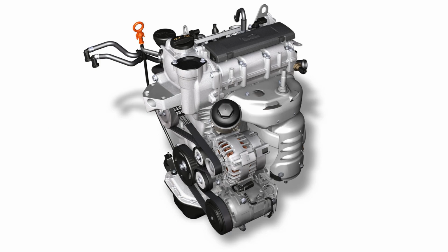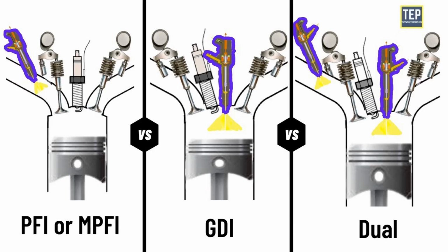Advantages compared to carburetor. Carburetor, mono-injector carburetor and mono-injector injection systems have passed into history for the reason that their operating principle did not allow to accurately dose the amount of fuel supplied in all engine operating modes and minimize losses in the warm-up mode. Due to the fact that gasoline was injected directly into the intake manifold, after a cold start most of the fuel portion was deposited on the cold walls of the manifold. Therefore, the mixture had to be extremely rich, which increased the consumption and harmfulness of the exhaust gases.